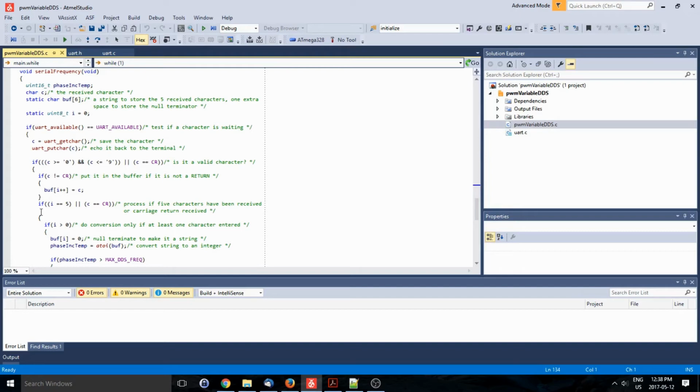And then you fire up a terminal program. Teraterm or Hyperterm, there's a couple of different ones that you could use. Putty is another one, P-U-T-T-Y. They just turn your computer into a dumb terminal. You just type a character, it goes out. Anything that comes back from the serial port will be displayed on the screen.